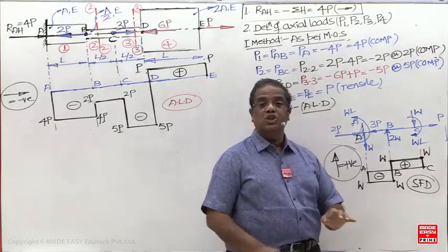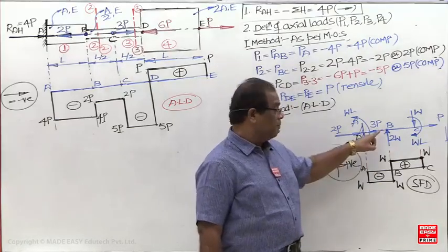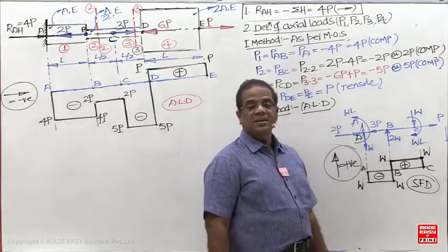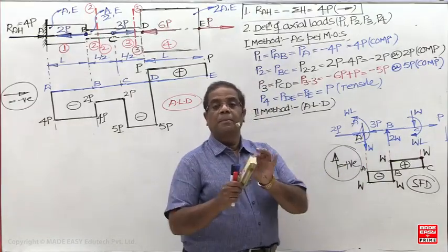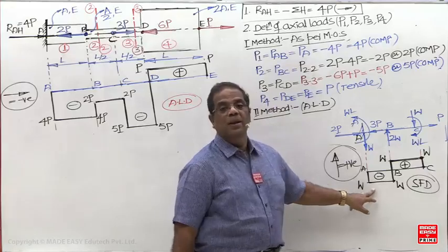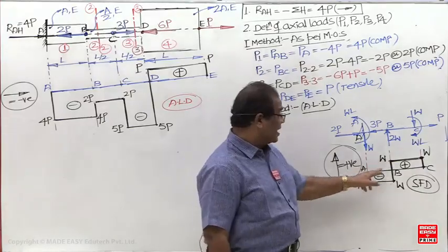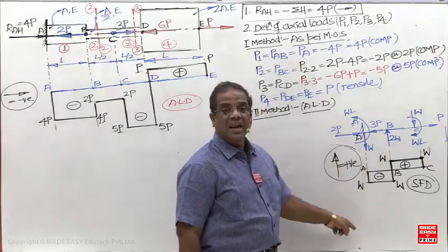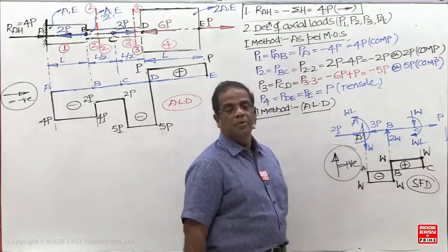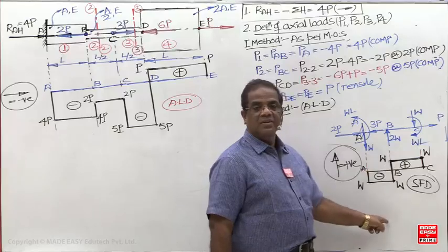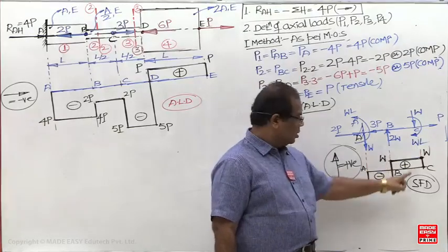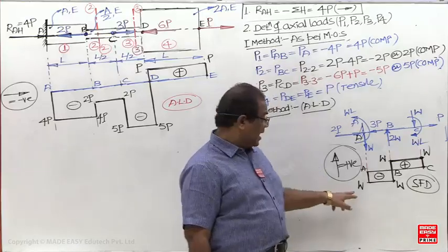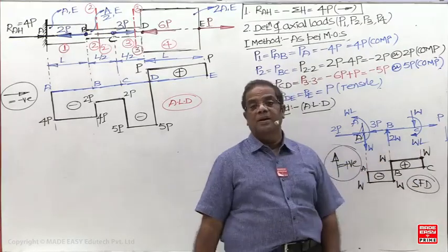What have you done so far? From the beam you have drawn the SFD. Sometimes the SFD is given in the objective question and they ask what type of loads act on a particular beam, for which the SFD is as shown below. Determine what loads are acting at A, B, C. How to decide? Three vertical lines. At A, a vertical line means a constant point load. What is the magnitude? W. At B, vertical line, magnitude 2W. And at C, W. So the beam is loaded by three constant point loads: at A, W; at B, 2W; and at C, W.